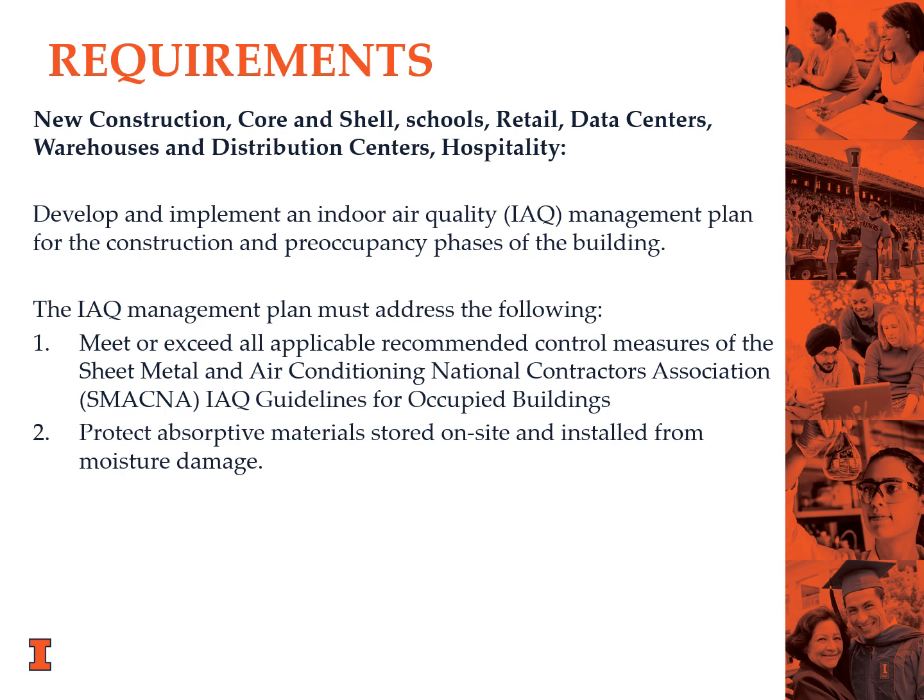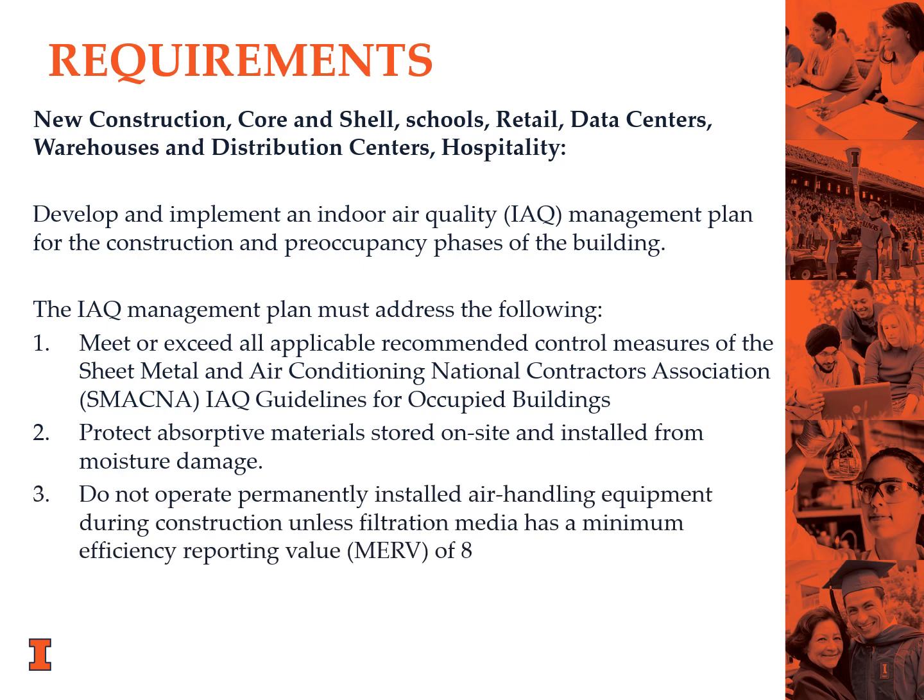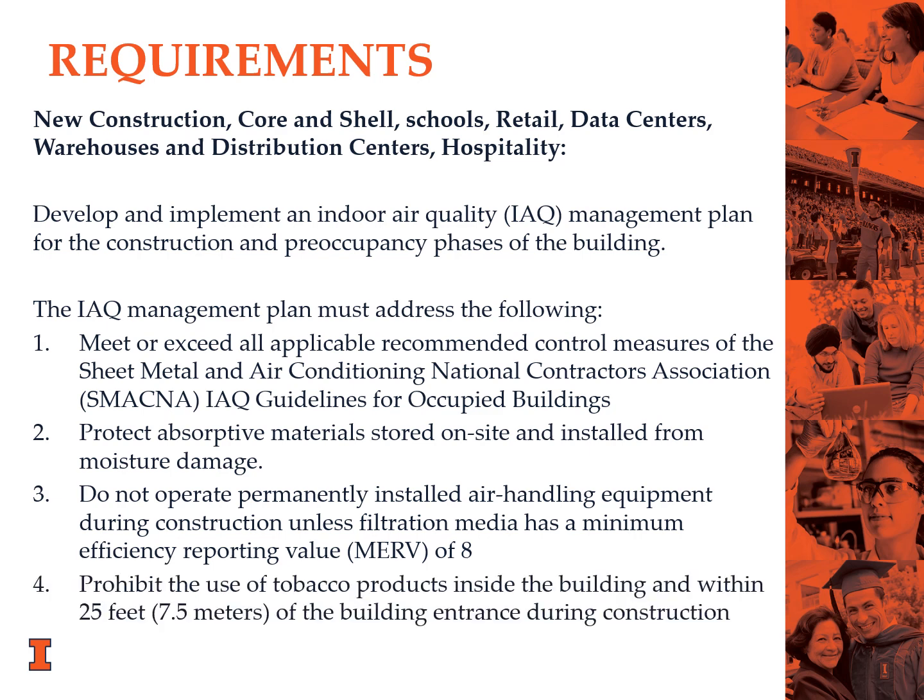Second, absorptive materials stored on site and installed must be protected from moisture damage. Third, permanently installed air handling equipment cannot be operated during construction unless the filtration media has a minimum efficiency reporting value of 8. Immediately before occupancy, all filtration media must be replaced with the final design filtration media. Lastly, tobacco products may not be used inside the building or within 25 feet of the building entrance during construction.